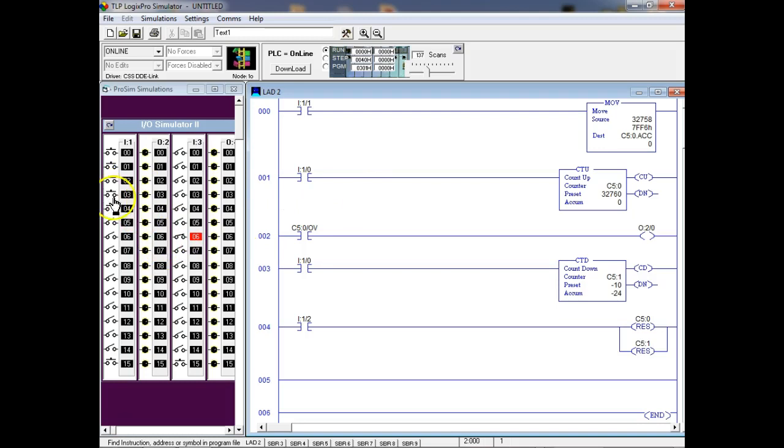So the down counter, let's see if it resets now. So let's choose the reset. Okay, it did. So normally, notice the down counter. So here's the down counter. And automatically, normally we preset it with a what? With a negative number. We're going to use a constant. And it's automatically done, right? Because this is greater than that. So as long as this is greater than that, we get it done. This has to go less than that for the done to go off.